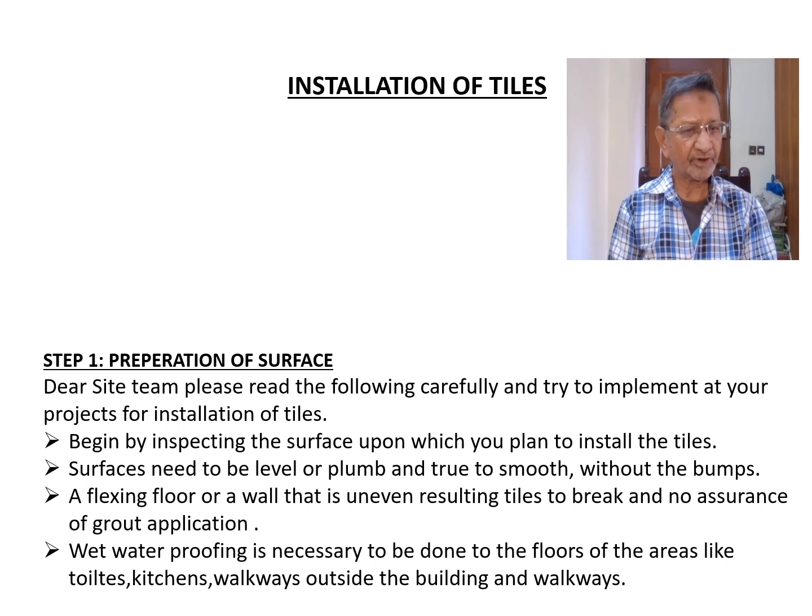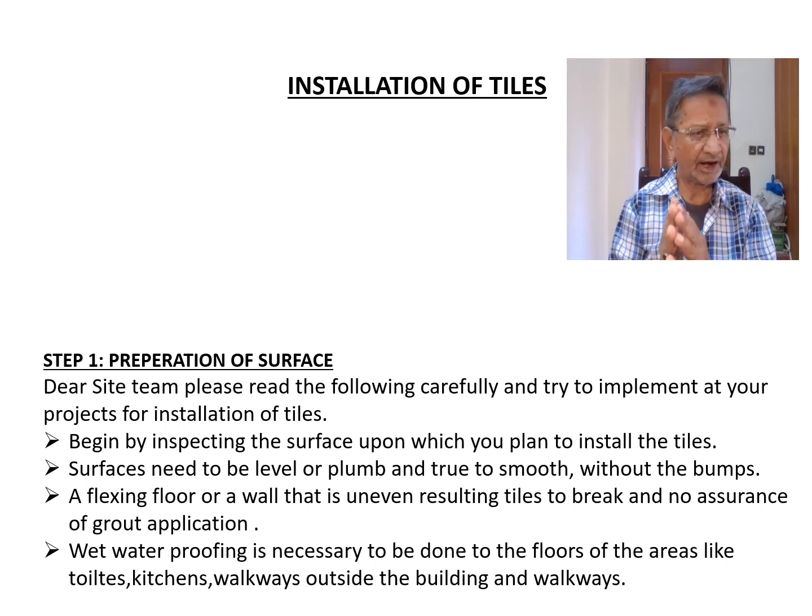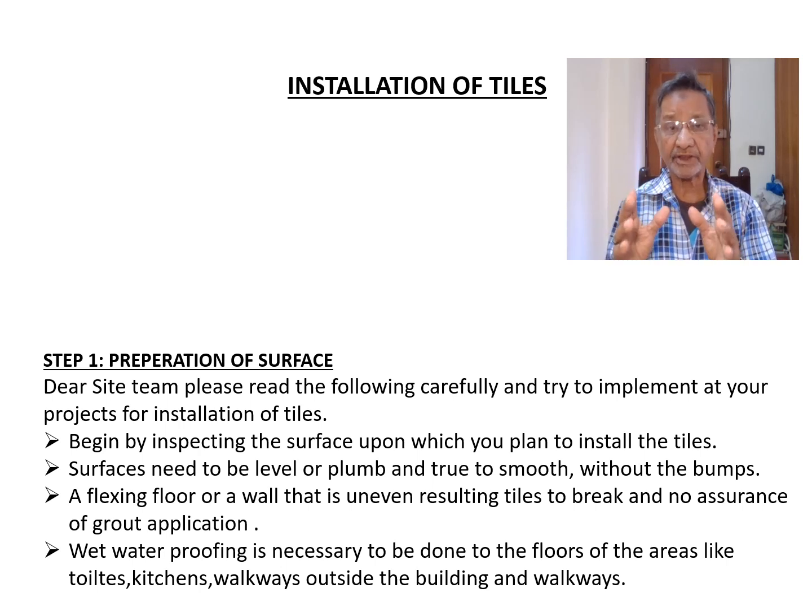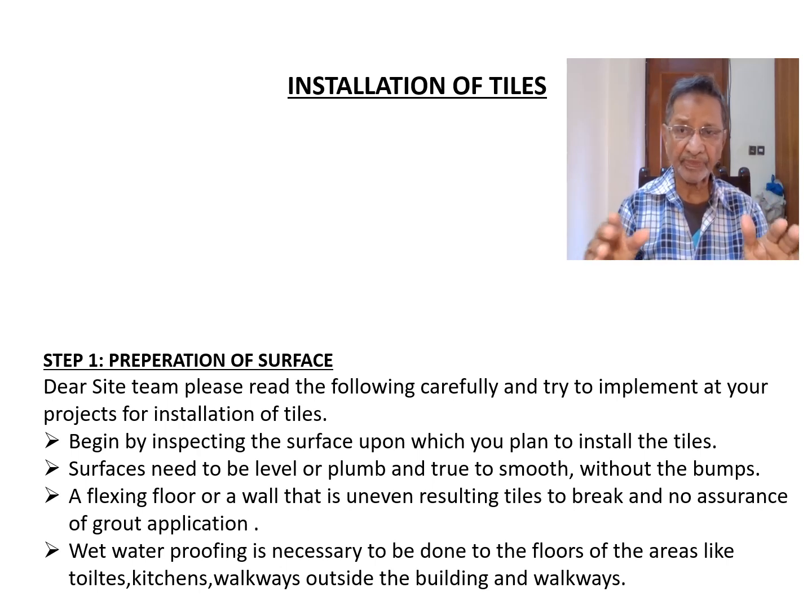Today I am going to upload a new lecture on the topic of installation and process of tiles. Number one, first of all, the engineers and supervisors who are looking after the project, my advice is that you must check the surface. The surface should be smooth, and it should not be uneven, and undulation should not be there, so that the tiles are fixed smoothly and rest successfully.